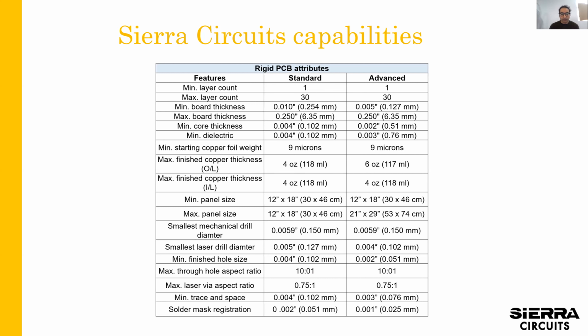It gets really difficult and hairy when you have laser drilled microvias, impedance structures, you're trying to hit a certain characteristic impedance, and your board is very dense. So your microvia has to be small. Therefore, in order to have the proper aspect ratio for plating that microvia, that determines the thickness of the dielectric, which impacts your characteristic impedance calculations. That's when it gets hairy, and all these design rules really do play off of each other, and you have to work with your fabricator to get it right.